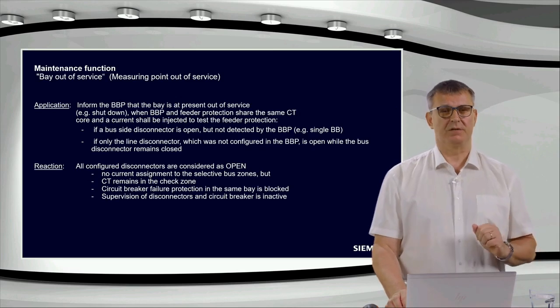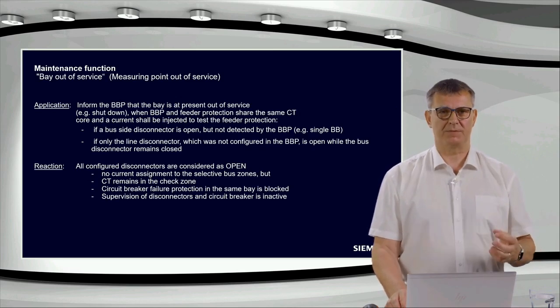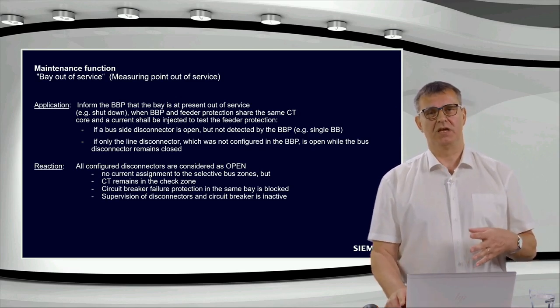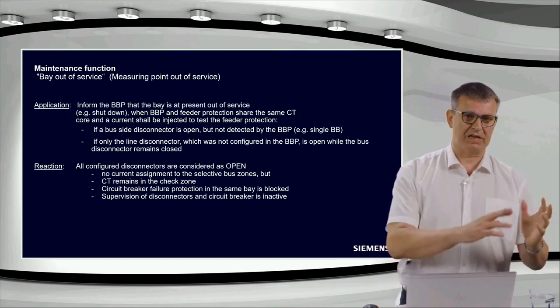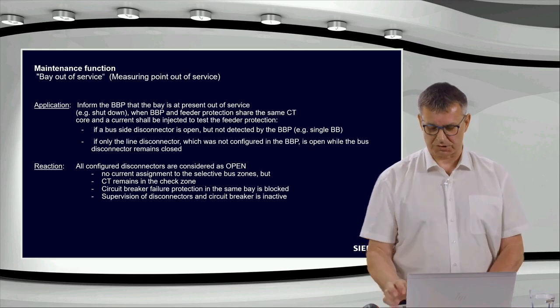You have a shared primary CT between busbar protection and line protection, and you want to test the line protection, the feeder protection, without affecting the busbar differential protection.